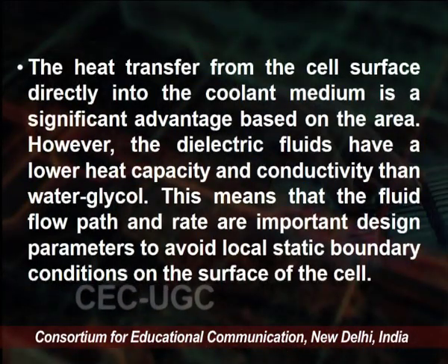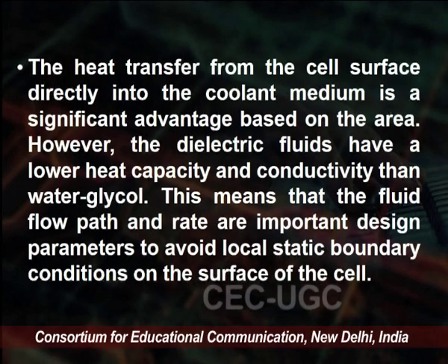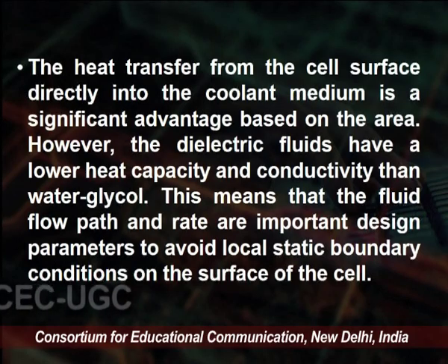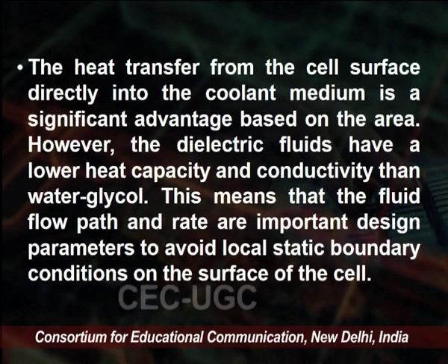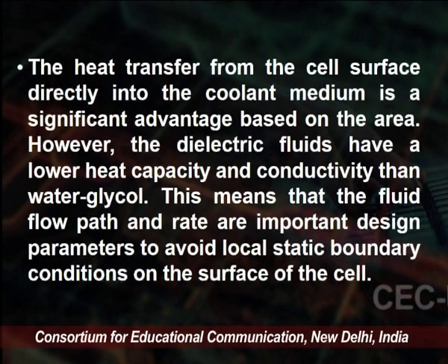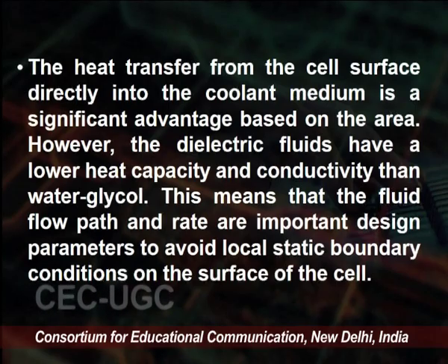The heat transfer from the cell surface directly into the coolant medium is a significant advantage based on the area. However, dielectric fluids have a lower heat capacity and conductivity than water glycol.